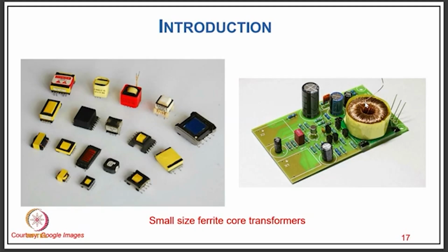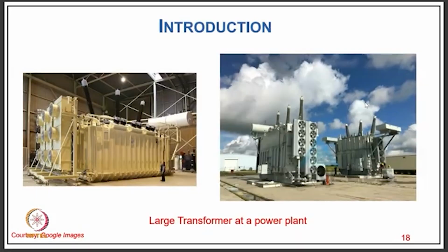isolated supplies. A typical example is the computer power supply, where you need a power supply for the cooling fan, you need a power supply for the motors of the floppy disk drive and hard disk drive, and you need a power supply for your processor. So all these DC supplies are isolated and they are of different voltages. So in the transformer you have several secondaries which give you different voltages, where you keep different numbers of turns.